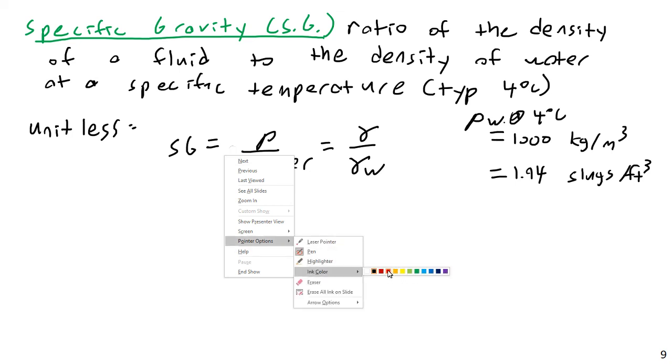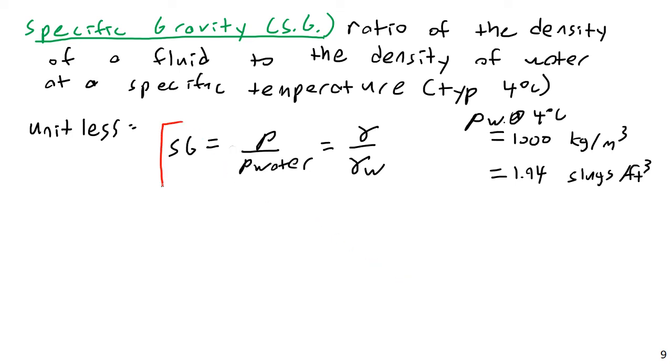I would really encourage you to know how to work an exchange between specific gravity, specific weight, and density. For example, in certain exam problems, I may not give you the density, but I may just tell you that this fluid has a specific gravity of 1.8 or something. And you will have to convert to density to put it into the appropriate equation.